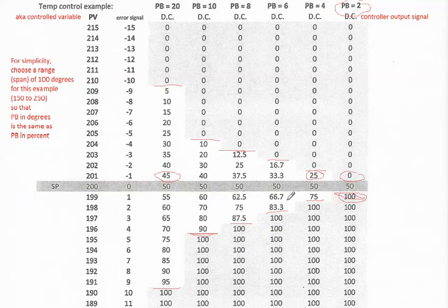So yeah, hopefully that illustrates some concepts. Narrowing the proportional band does give you tighter control because the control signal is going to react more for a given change in the process variable. However, if you tighten up that control by narrowing the proportional band too much, you can start to get into oscillations. Of course, we can talk about that whole thing I just said in terms of gain. You crank up the gain, but you have to be careful of cranking it up too much.